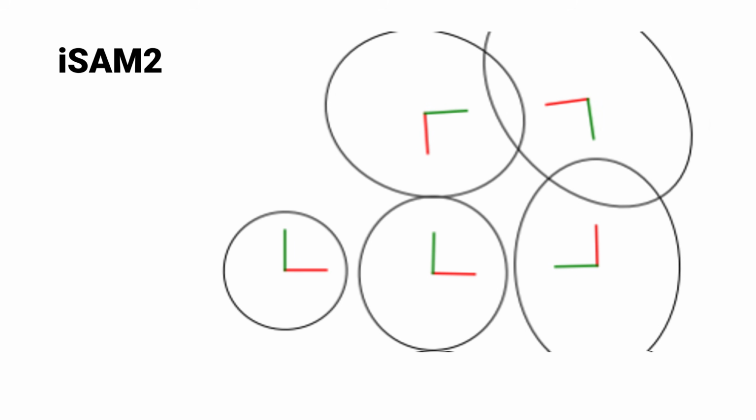The catch here is that iSAM is performing this at every one step. It's only taking the previous step and adjusting everything else. Instead of a full batch bundle adjustment or factor graph method where you solve for the entire thing, you're only solving for the previous step. This is super useful because you can do this real time on a small robot, and which is generally enough for odometry. Note that this will drift over time because there is no final adjustment like we did before.